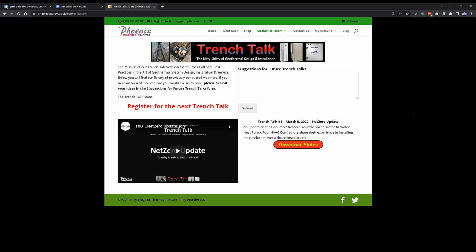So on a particular job where you're looking at the cost of electricity and the incremental cost of the pumps, I'll leave that up to you to do the math. But every time we've looked at it, these ECM pumps are ideal for geothermal applications. And they're ultimately cost effective because somebody's investing literally hundreds of thousands of dollars to have geothermal. If we saved $2,000 on a pump or pump station, are we really doing the customer justice after spending so much to get geothermal?